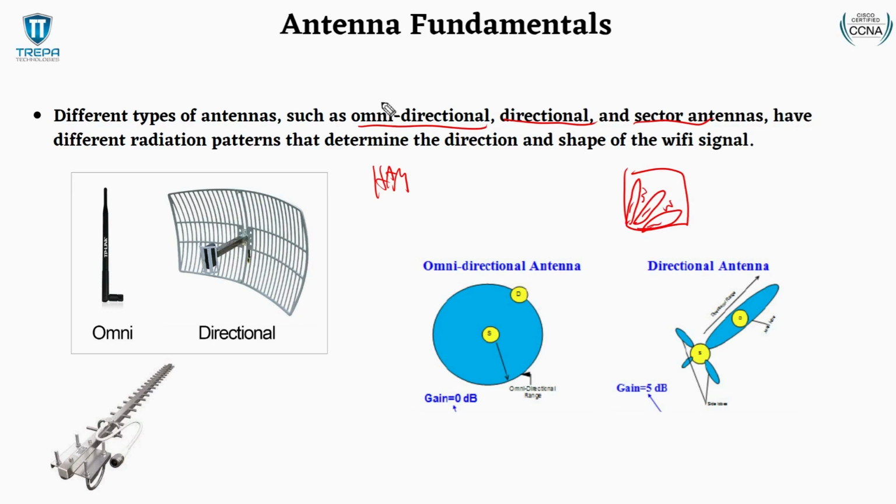So kind of self-explanatory. In a directional antenna or unidirectional antenna, what you're going to have is a strong Wi-Fi signal in one direction. So if we have 360 degrees, that direction could span maybe 45 degrees of that segment, right? But essentially the point is the back area and the side areas don't get any signal. And you may get some little lobes here, and that's just what happens sometimes when you push out signals. Signals sometimes go this way.